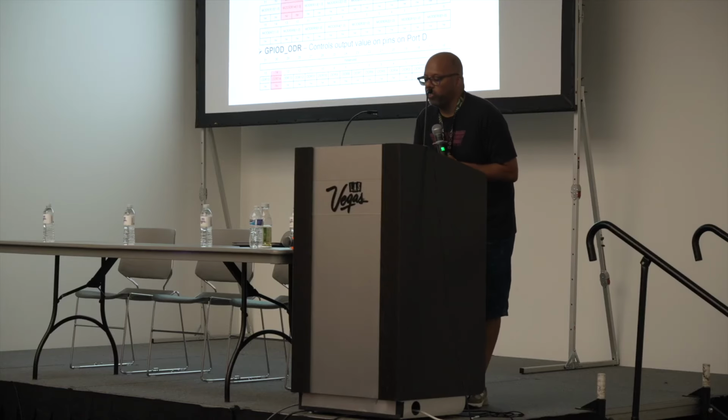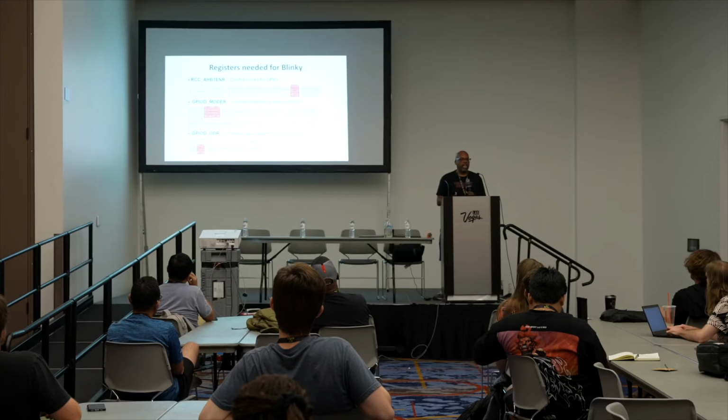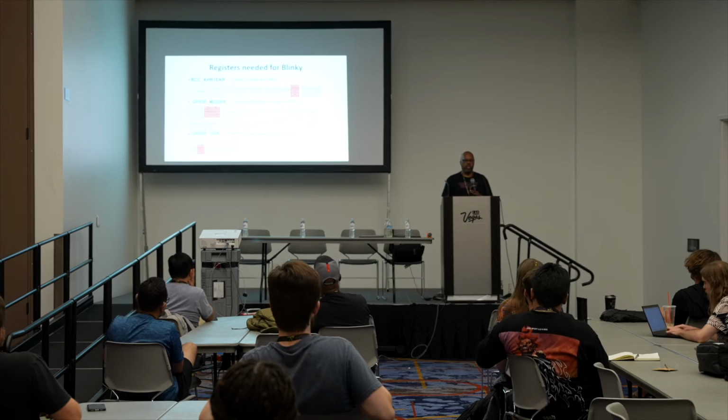So notice this register has got 0 through 15, right? Up there on the top. That's half the bits in the register. All the registers are 32 bits, right? So I'm just looking at the first half. And if you zoom way in on this, it says GPIO-D-EN for enable. And then in the data sheet, it'll say, oh, pin 3 on this register enables the clock to GPIO port D. Okay, so you got to set that bit to a 1.